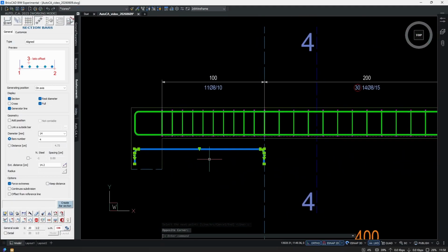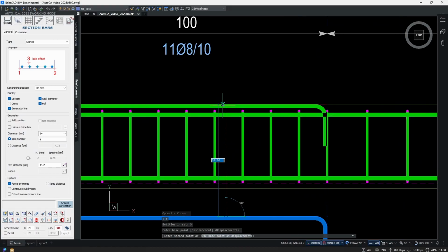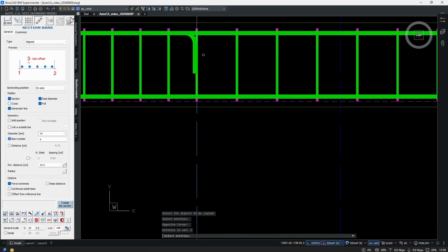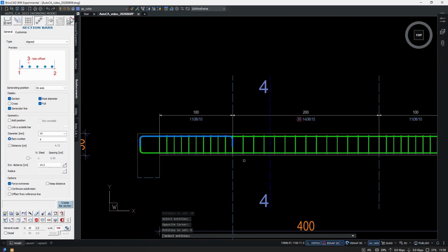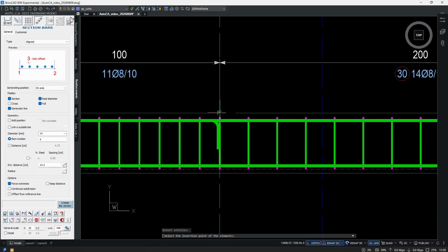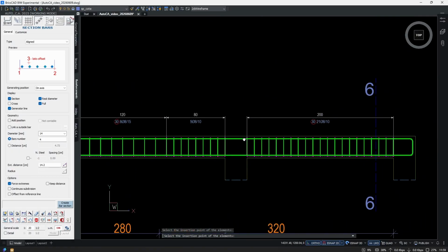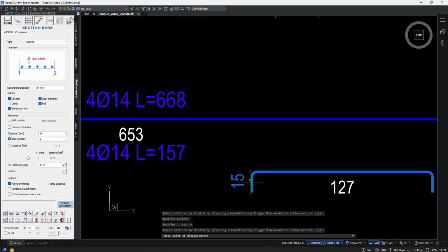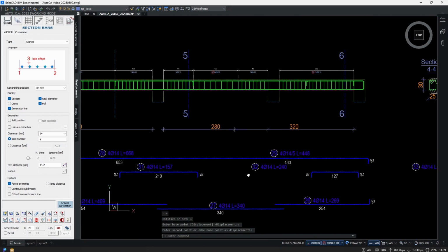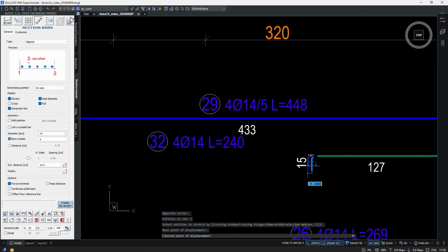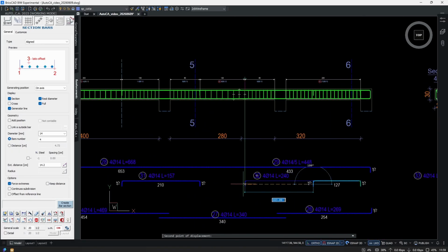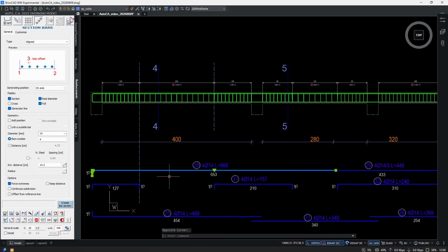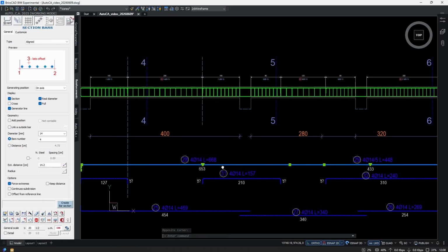Okay, the inside bar follows the same shape. I'm going to put it up here. And now I just need to copy this shape to the other positions as well, like here and also here. We need some stretches all the way to here, and this one needs to be stretched to this point. So these are the auxiliary rebars that help these upper bars.